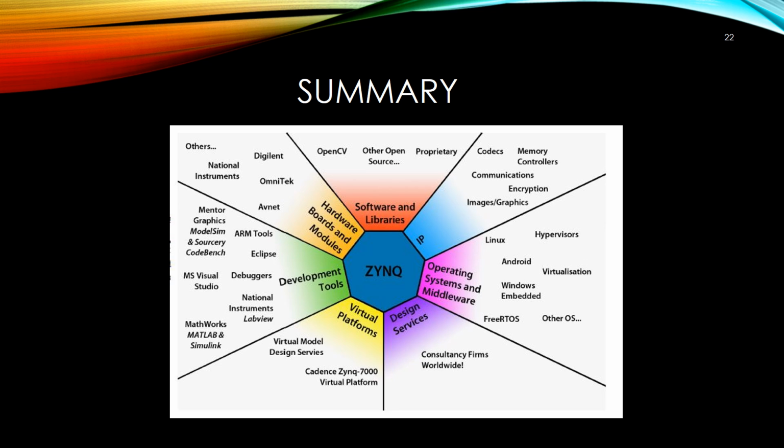The structure and resources of the programmable logic section were outlined, including the fabric logic, block RAM, and DSP48E1 resources and interfacing resources, and the important issue of interfacing between the PL and PS using AXI was also reviewed. Lastly, a comparison was made between the device members of the Zynq-7000 family.